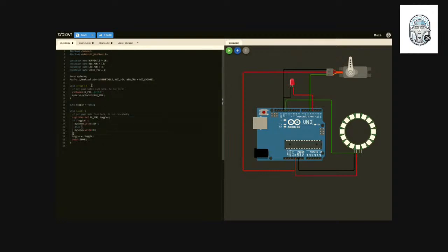All right, so now they still won't do anything with the NeoPixels. For the NeoPixels, you'll have to call a routine called begin. And that can happen when you're ready to use them. We'll also just add a clear, so it's all set to 0. And then here, let's try, we're going to add pixel index, and we're going to set it to 0. And then we're going to turn one pixel on at a time.